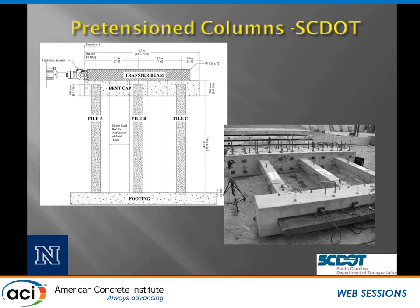Now, I just threw this in a slide. This is another project that we did. This is the one with the University of South Carolina. What I find interesting about this is that they've just taken piles that come up out of the ground, and they've taken a cap beam, and they just cast it around the piles. Okay? There's nothing that connects the piles to the cap beam other than the piles themselves. There's no reinforcement that extends out of the piles. There's nothing other than the pile itself with the cap beam.